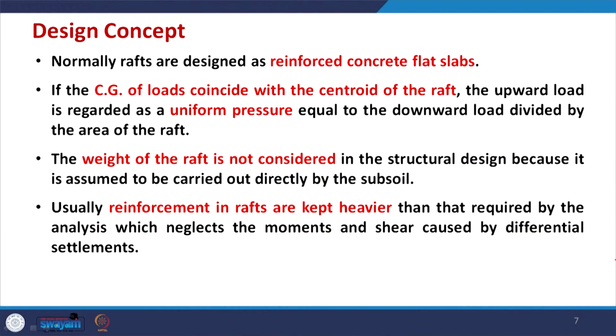Usually reinforcement in rafts is kept heavier than required by the analysis, and the reason is simply because the analysis which you carried out neglects the moment and shear caused by the differential settlements. So, it is conventional that raft foundations are more heavily reinforced than what you find from the calculation. Continue with the design concept.